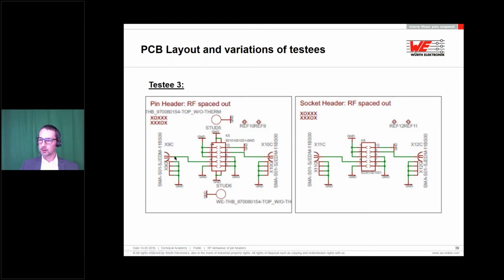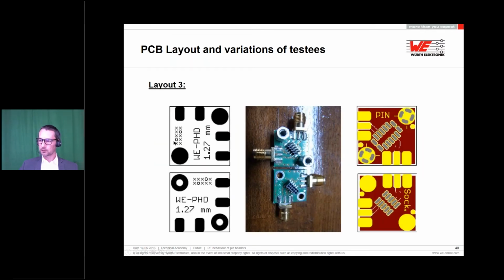And that's why we come in here on one pin, and then we separate the two signal pins with a line of ground pins and go out here on the other side. So you can see it easily here on the keying, the two pins that have the signal, and there is one line of ground pins in between. So again, here the keying picture, and here you really see the distance between the traces.